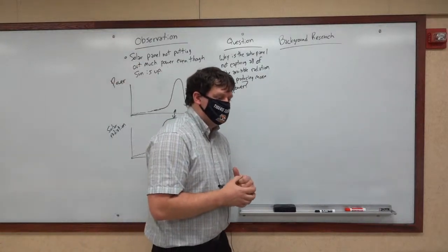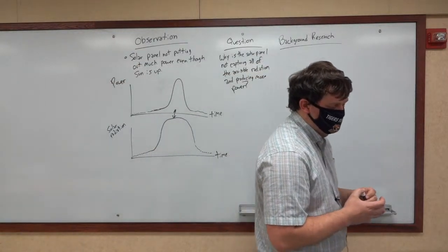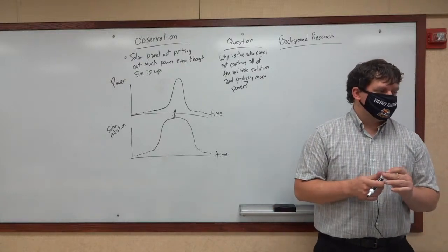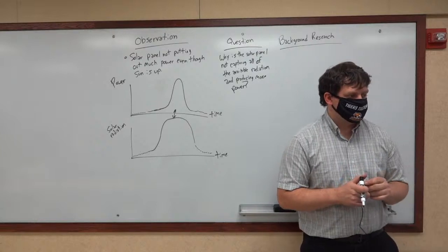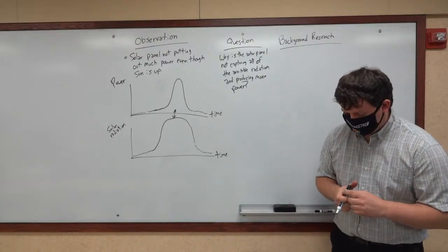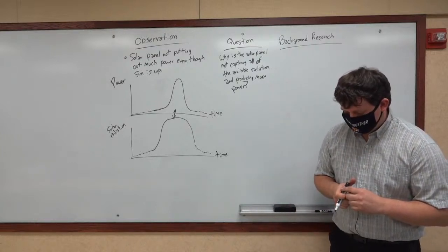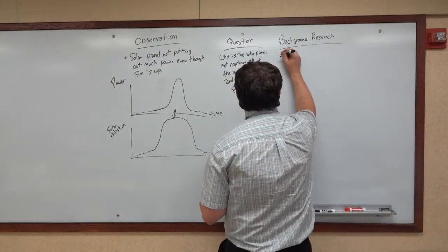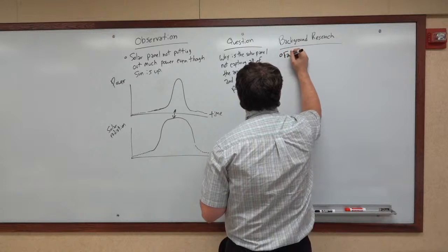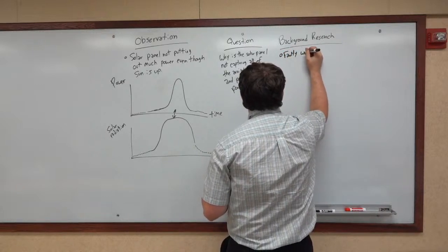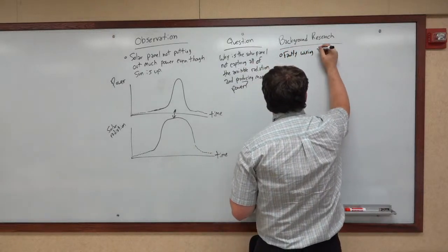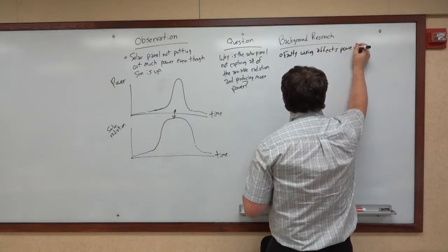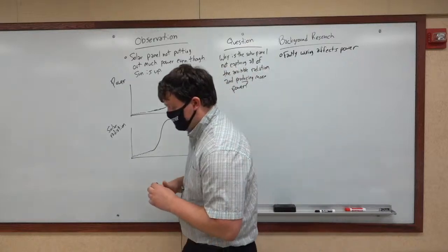Okay, so one of the first things that I found that's pretty prevalent is that this problem, also known as zero power output, can be caused by a damaged inverter or a faulty charge control. Okay. So there's one piece of information.